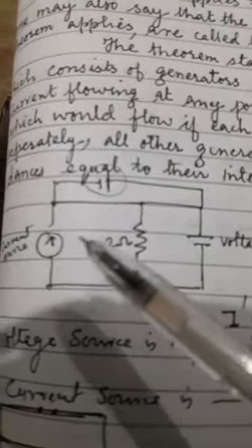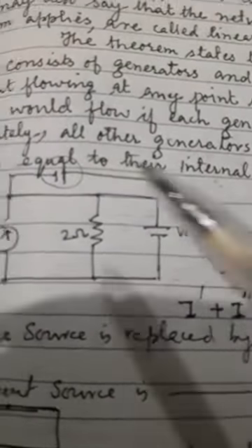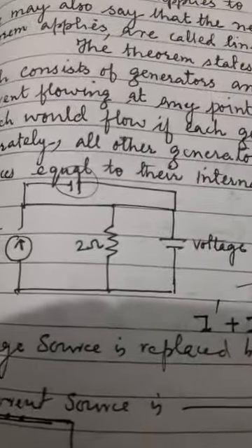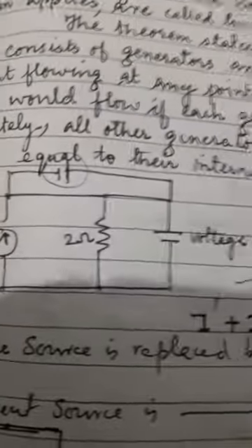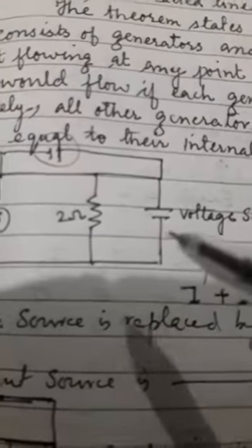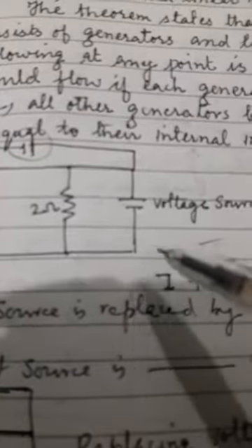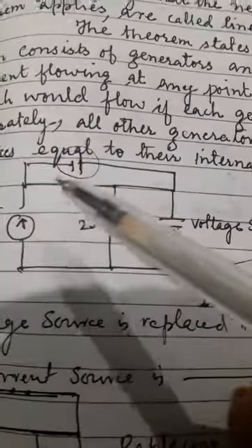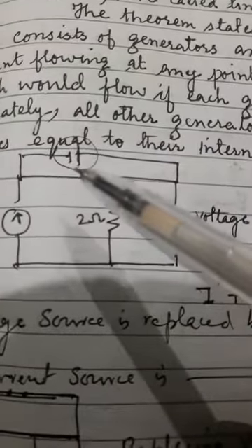It tells us that whenever you have a current source and voltage sources, here again a voltage source, you will take them stepwise. For example, you are cancelling this voltage source number 1 and this voltage source number 2, replacing them with their internal resistance.